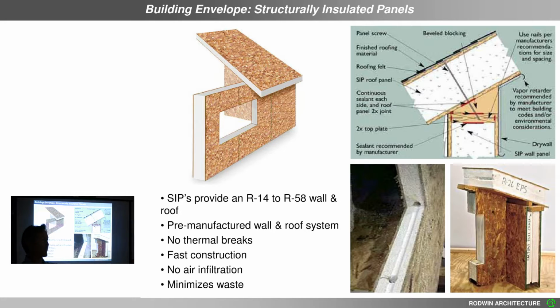Plywood was one that came out 50 years ago, and 20 years ago they came out with the newer generation called oriented strand board. The nice thing about both plywood and OSB is that they are structurally predictable. You know exactly what their engineering capacity is, so you can use less of it. When a structural engineer doesn't know what the structural properties of any natural material are, they have to overcompensate because there might be a weak spot.